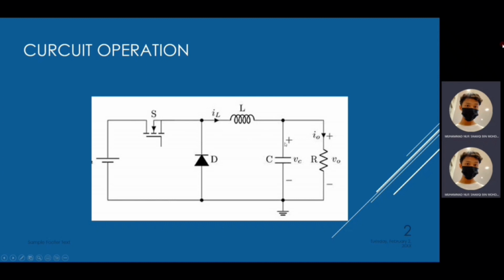As a result, diode D1 is inhibited by the positive voltage at the cathode in the opposite loop. The current is routed to the resistor and the capacitor. The phase results in the collapse of the magnetic field of the inductor. The inductor voltage becomes more polarized as a result.